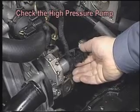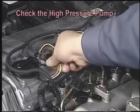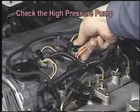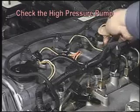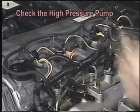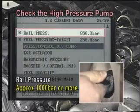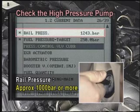Now that we have determined that the MPROP is normal, the high-pressure pump should be examined using the closed system method for checking performance. During this time, all terminals of the MPROP and the injector should be removed, and then the engine should be cranked. Lastly, check the rail pressure value on the high scan. For the above vehicle, the rail pressure is about 1,000 bar or more. Thus, in this situation, the discharging performance of the high-pressure pump is within normal range.